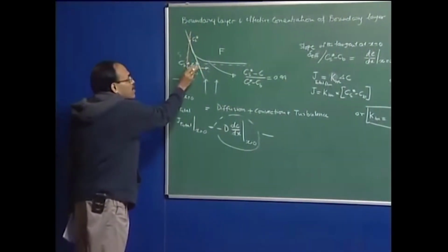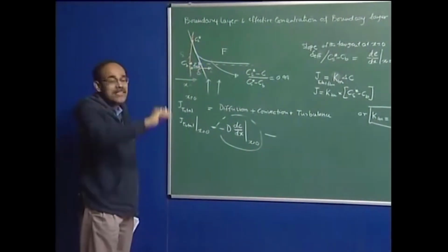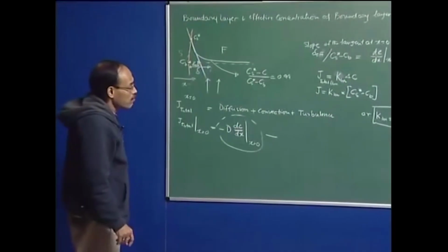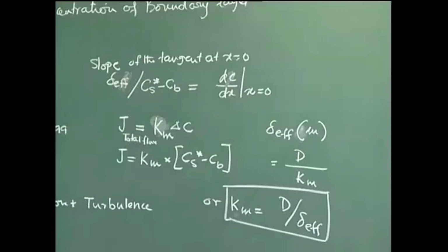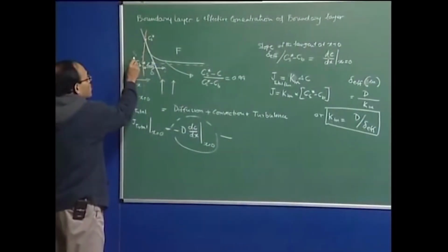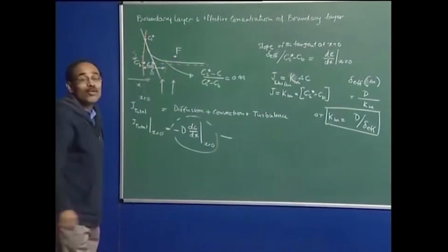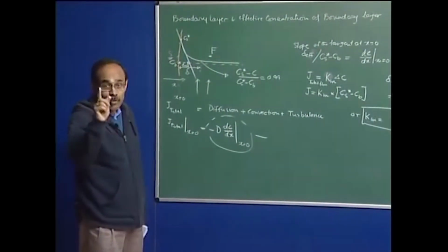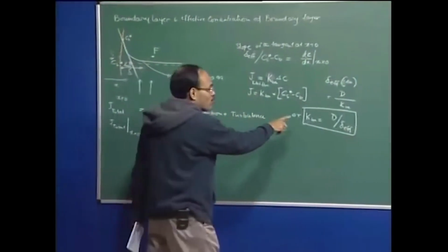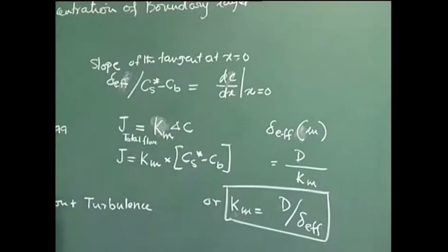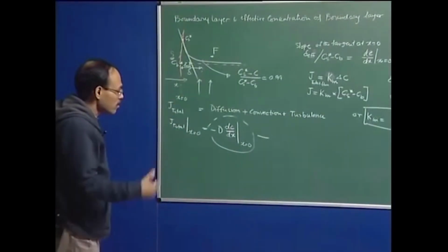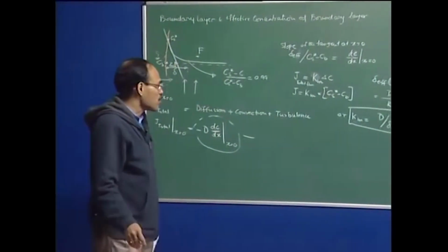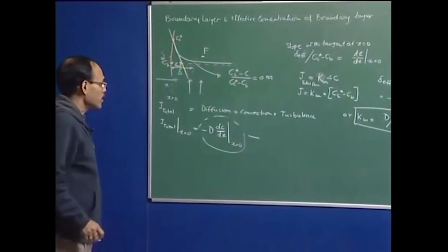which essentially means this distance will become less and less, provided the current of fluid past the solid is more intensive. Km is proportional to D to the power 1 when we are talking of mass transport between a solid and a fluid. But if you are talking of mass transport between two fluids, it is found that the mass transport coefficient becomes proportional to D to the power half, which one can show from Higbie's model, of course, which we are not discussing here. If you have taken any kinetics course or mass transport course, you know this already.